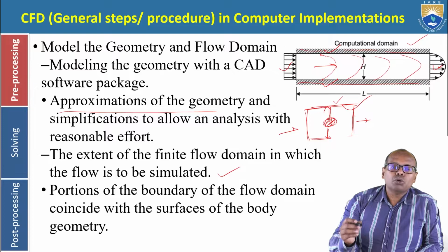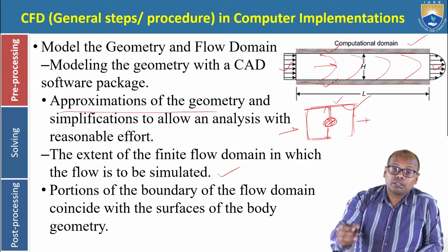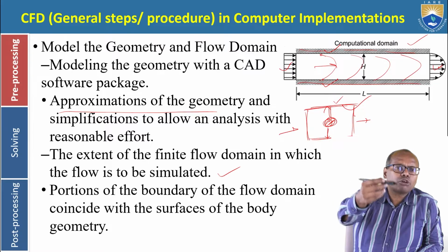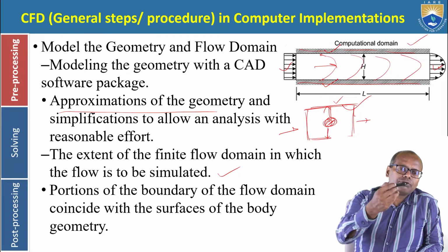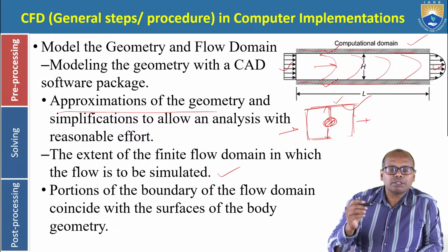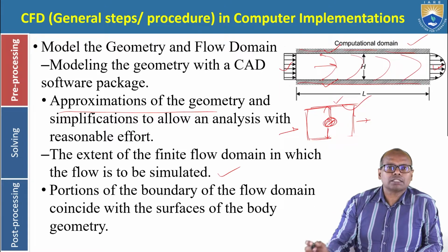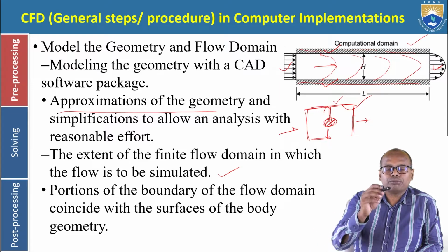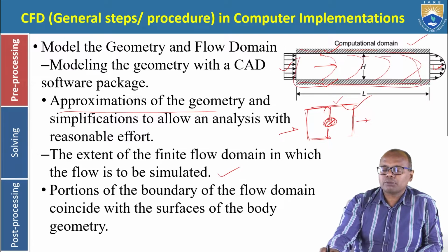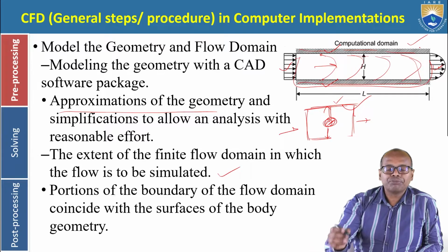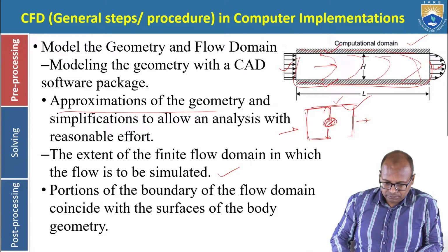The real domain is given: the parallel plates are there, the heights, the lengths, the widths of the parallel plates, and the distance between the parallel plates, all these things are given. So based on those things, we have to find out what domain is required for my simulation. Okay, so that is the first step.